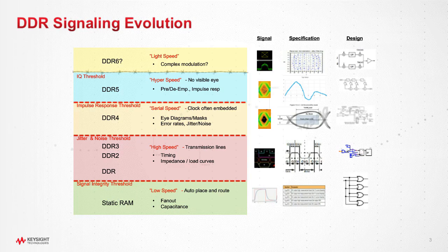So what do we do? Well, again, the industry can draw on other technologies that have had to deal with this kind of problem for a long time. And the latest generations of PCI-Express are an example of that, where there actually may not be any place in the system that you can probe physically and see an open eye, and yet you have to be able to move data from point A to point B. Now, that's something that is understood with JEDEC, but the question is, how do you apply that in a memory environment?